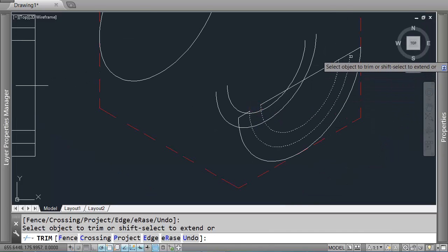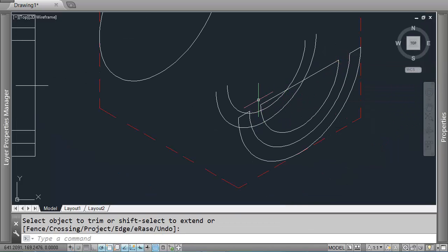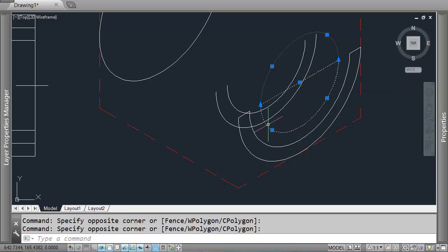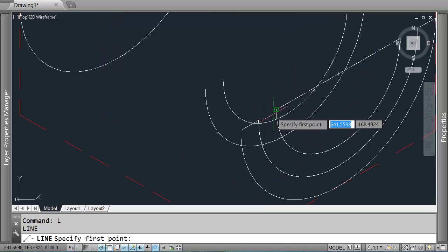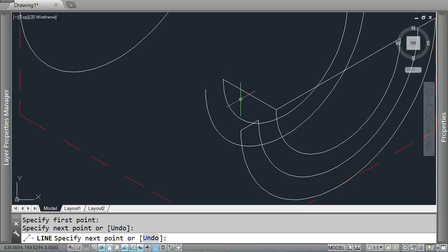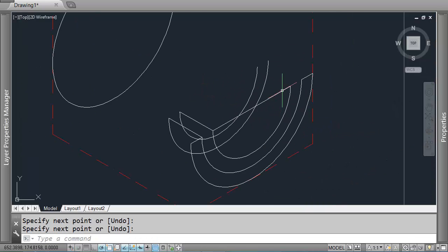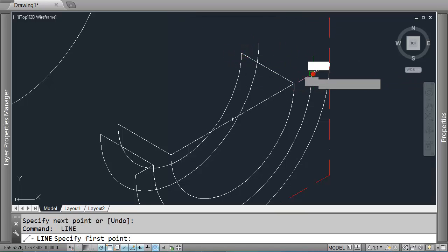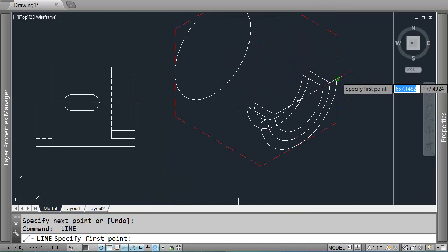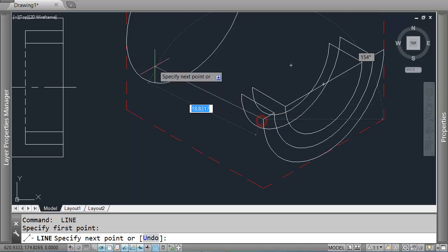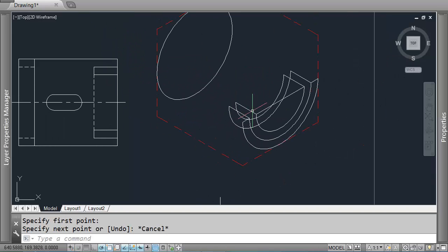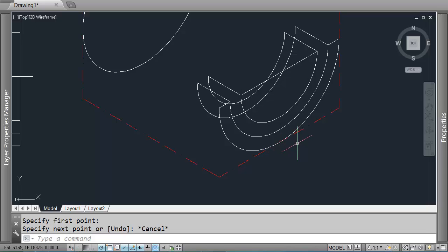So basically how this is going to show up, we have these selected objects forming a solid, and these selected objects are also forming a solid, and then we have a gap in between. It'll help if I start to join up some of these lines. So coming back at 30 degrees through my 6 units, I can join up these lines, I can join up these lines. This one will be some 23 units, it won't go all the way back, so I won't put it on just yet. Neither will this one. I won't draw those lines just yet because we're not going to need their full length.